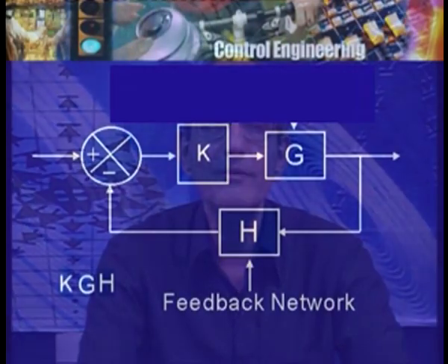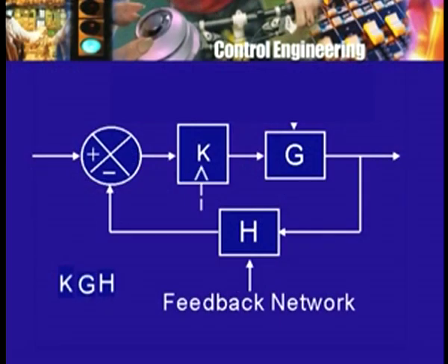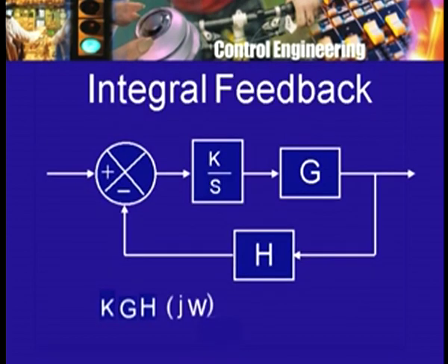The simplest thing to do is, of course, change the gain K, and that was the case we studied first, for the case when we had just proportional feedback, but the amount or the proportionality constant K here could be changed. The second thing that we did was not just have K here, but change the transfer function to K by s, that is introduce an additional transfer function 1 by s, corresponding to the integrator. Now, that resulted in certain changes and certain consequences of that, such as the system could become unstable for a value of K greater than some critical value.